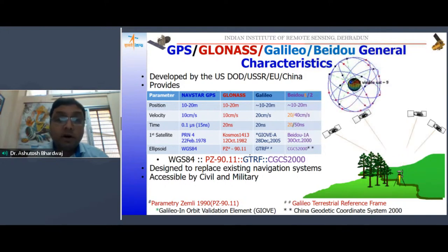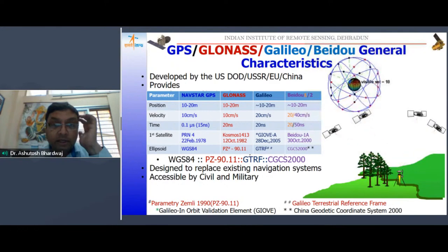Okay, so now all the four systems are in different coordinate systems, which are very near to each other, but still they are different. But now we are in a good era, so all the countries and agencies owning these systems are cooperating. The transformation parameters are known, and thus the satellites belonging to any of these can be utilized for generation of the coordinates.